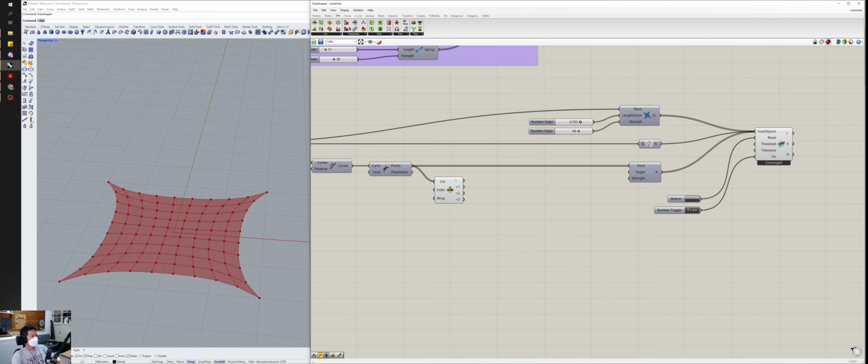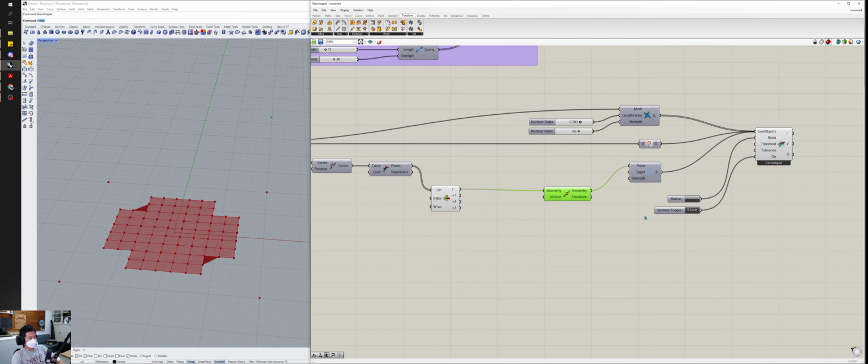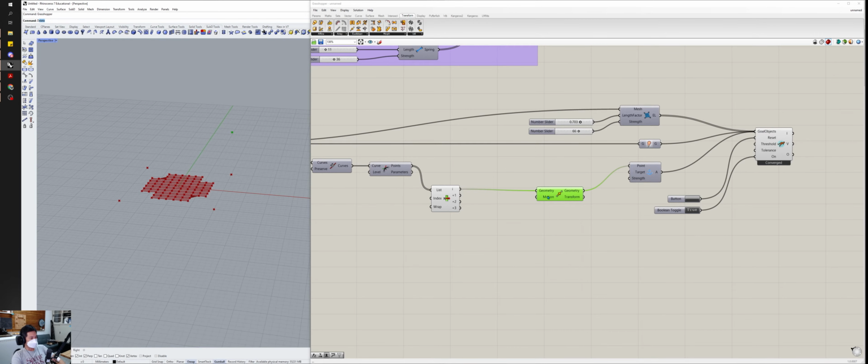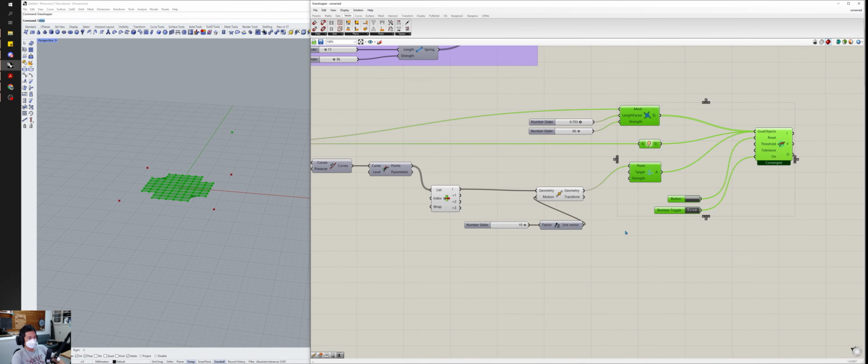And then I'm going to use a move command, so that I can move them around. And I'm just going to use the same move command for each of them. So let's say move, it's going to be like this, and that's going to be 1 point there. And you can see that that move moves it up. By default, it moved up 10. Let's change that so that it's a slider that we can control. We need to define the direction. So let's say Z. So a factor of 10 and then a motion Z. We probably need a little bit more space here.